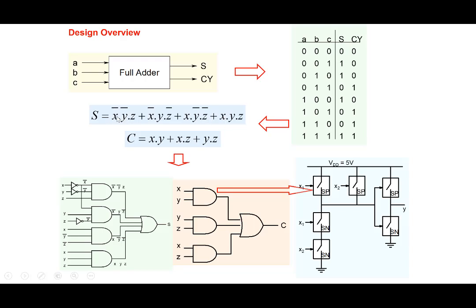This expression we can see here has 3 terms in it, while this has only 2 terms in it. So this term is simpler than this particular term. How is it simpler? Well, you can see here a term like this requires a 2-input AND gate, while a term like this here requires a 3-input AND gate. So that's how this expression is simpler. Not only that, this has 4 terms in it, and therefore it requires 4 gates here. And then it requires a more complicated OR gate also. It requires an OR gate with 4 inputs. Realize that an OR gate with 4 inputs is more complicated than an OR gate with 3 inputs. So we can see that this is a complicated expression. This is a simpler expression.